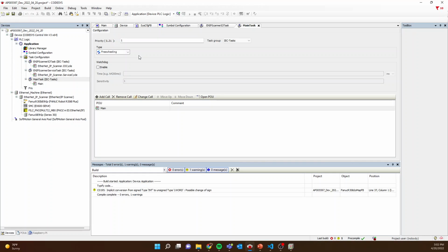And one of the large benefits of using Codesys is actually the cycle time to run our main program. It's in the microseconds, I believe. So it's very, very quick in comparison to a program in Allen Bradley controllers. Largely, I think that's due to how the code is compiled and how it's executed on the runtime. I haven't looked too much into that either, but I have noticed that the cycle times are really quick. So that's kind of a cool feature.